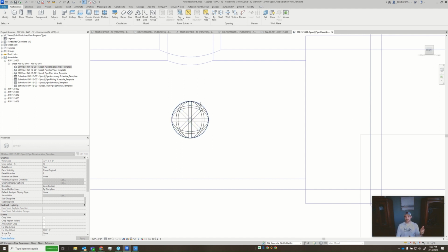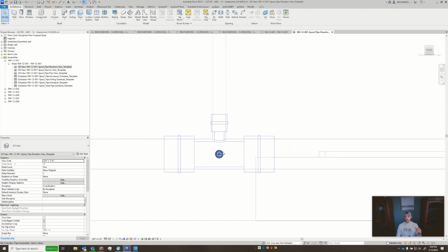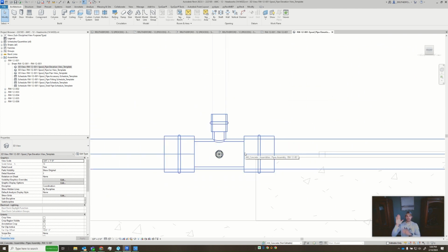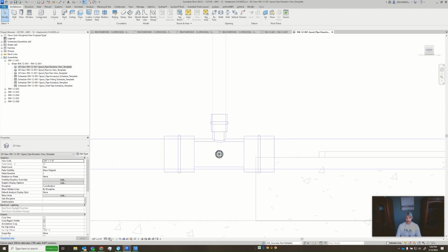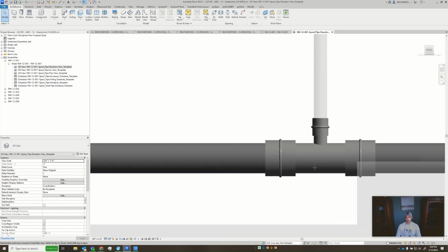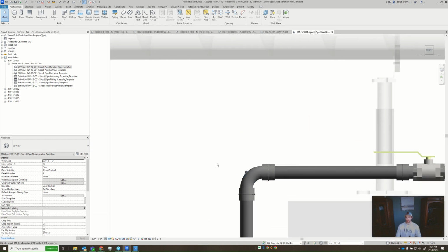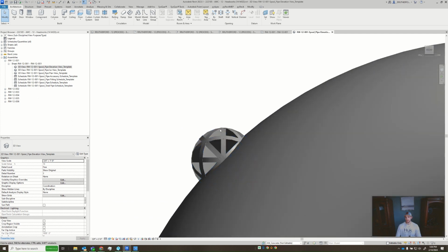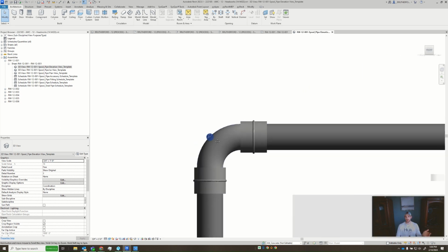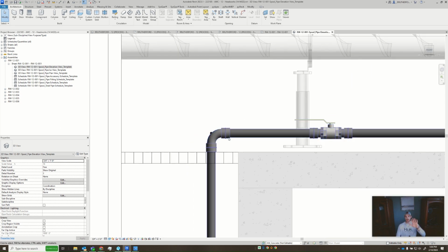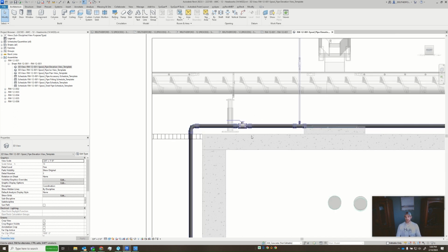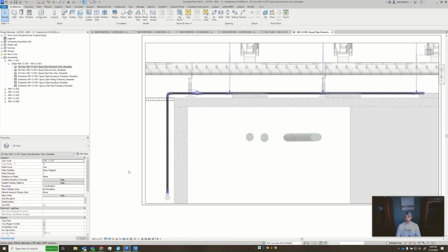So for this case, these atoms come in handy. I will pick this circle here, click on that, and now my work plane is tied to the face of that circle. And again, I'll go ahead and show you the shaded version here. You can see why that works, because these atoms have 3D elements to them, so they have faces. So when you select that face, it automatically sets that as the work planing face. So that's a really nice feature that is included there with those atoms.